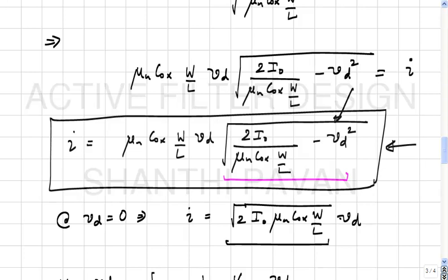And if each circuit is nonlinear, let us say it produces harmonics, right? Second, third, fourth, and so on. When you find the difference between one being operated with Vd and the other one being operated with minus Vd, all the even harmonics will cancel, only the odd harmonics remain, and this is an attribute of all differential circuits, correct? Even if they're nonlinear, you understand? If they're linear, then there's no question of harmonics at all. If you have two nonlinear circuits and operate them in a differential fashion, then if you look at the difference between two node voltages, which is what your output quantity is, all even harmonics go away, right? This is one more advantage of differential operation. Is this clear? Okay.